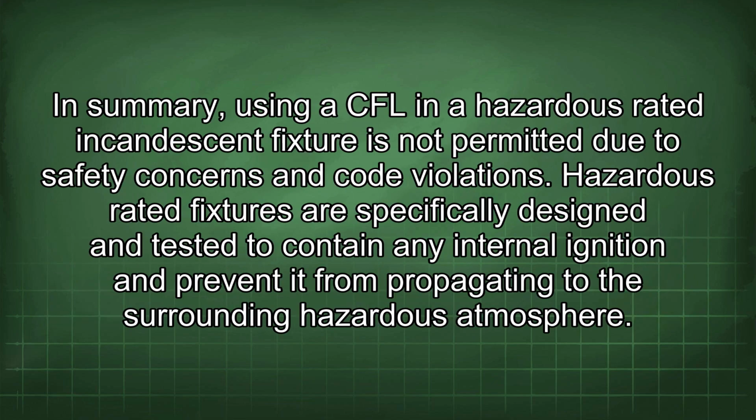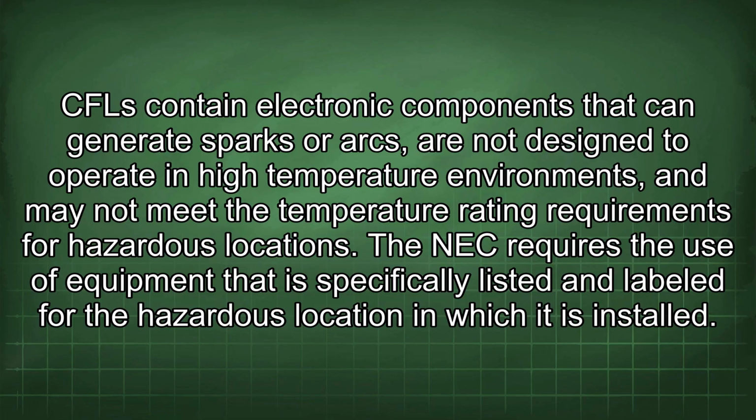In summary, using a CFL in a hazardous rated incandescent fixture is not permitted due to safety concerns and code violations. Hazardous rated fixtures are specifically designed and tested to contain any internal ignition and prevent it from propagating to the surrounding hazardous atmosphere. CFLs contain electronic components that can generate sparks or arcs, are not designed to operate in high-temperature environments, and may not meet the temperature rating requirements for hazardous locations.